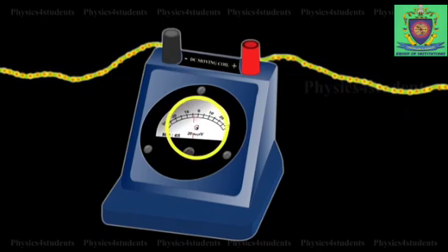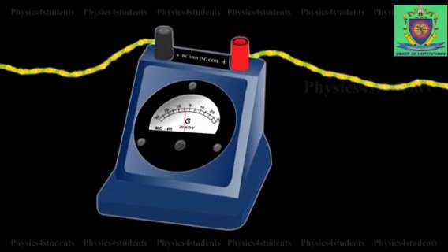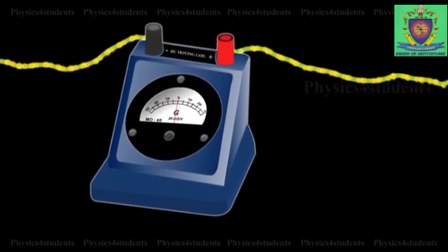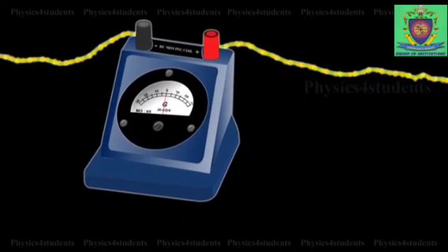See, when you consider the galvanometer, for the conversion to an ammeter, the current should pass through that, where here I need to consider parallel combination. Okay, I need to consider parallel combination. Here, whatever you are seeing, the galvanometer scale is very small. Just imagine if a large amount of current is passing through it, it cannot show that much deflection.